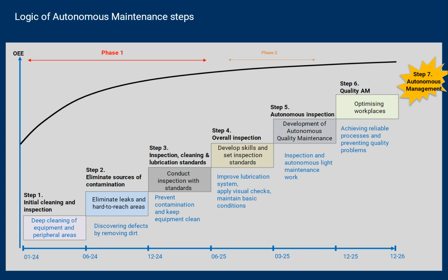The second phase of the Autonomous Maintenance Development Program covers steps 4 and 5, which aim to prepare operators to achieve a high level of technical competence and gain deep knowledge about their equipment. Through this training, operators will be trained to identify both hidden equipment defects and quality problems arising from machinery parts and systems. The main activities in this phase focus on equipment inspections, quality, safety, as well as environmental aspects, as part of a routine system of work area management.